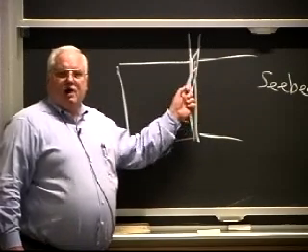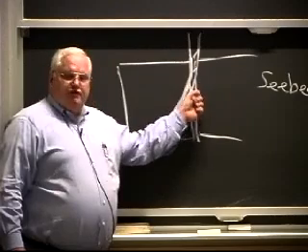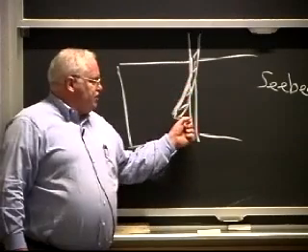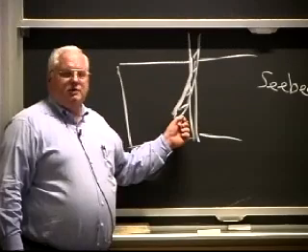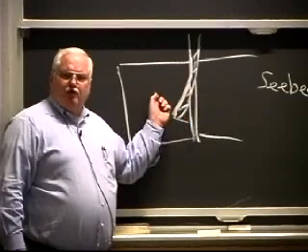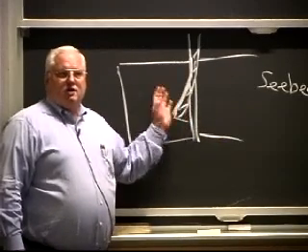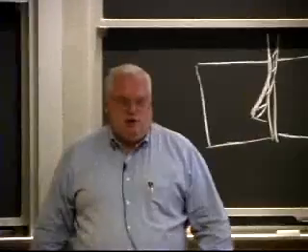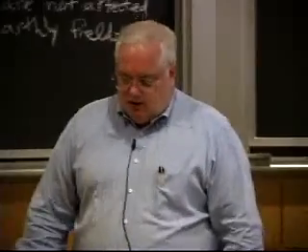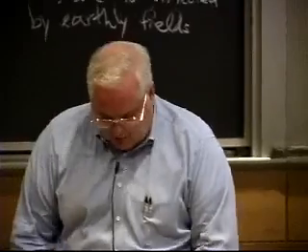And that voltage will drive a current. So if I'm welding 2 different steels in a very heavy section, people find that it's impossible to keep the beam straight because you actually generate a voltage within the material, set up currents which set up magnetic fields which bend the beam. There is no known solution to that. Okay? So they tend not to use it.